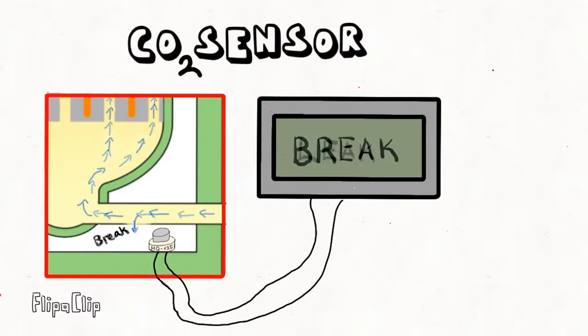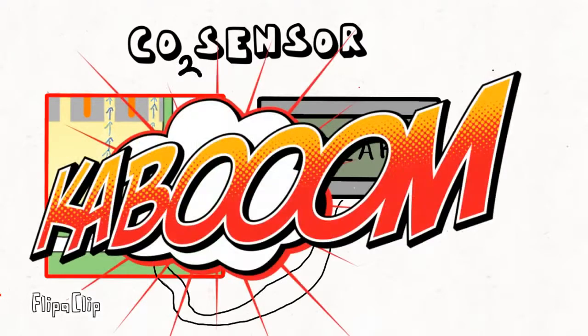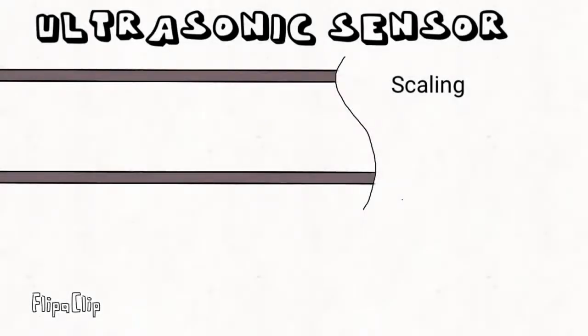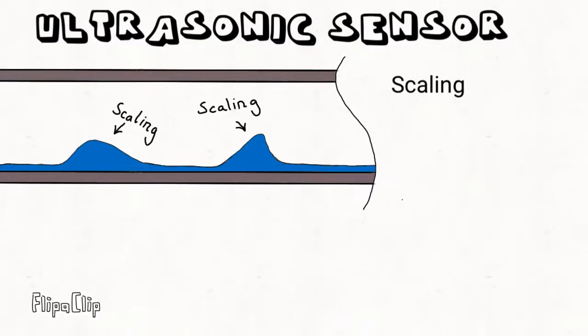The leak before break concept is used for this application, which ensures that a leak will develop before a catastrophic rupture can occur. This is a very important aspect which prevents the nuclear power plant from a major disastrous event like a nuclear meltdown. Finally, we see the ultrasonic testing of pipes for detection of scaling and cracks.